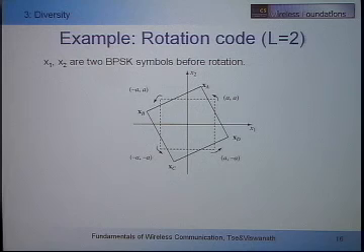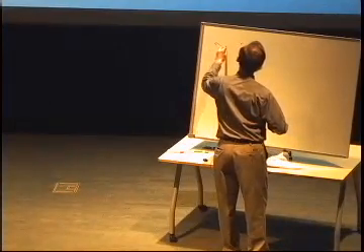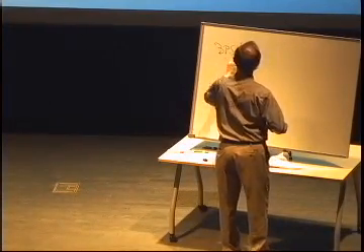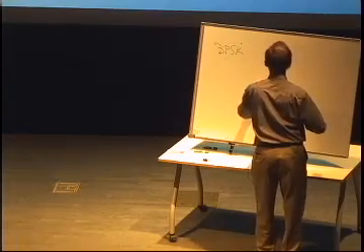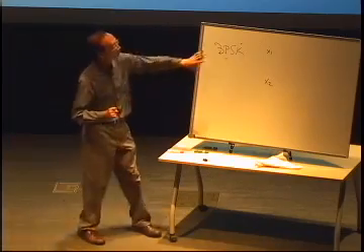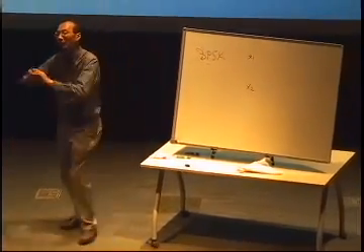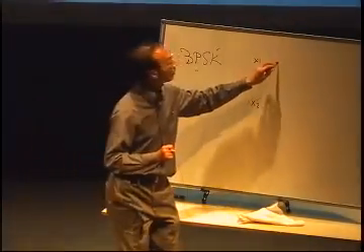So now, I have 2 symbols. BPSK symbols. Okay? X1, X2. I want to send these 2 symbols, 2 information symbols, actually, over 2 time instances. I'm assuming you have done interleaving so that these guys will see independent channels.